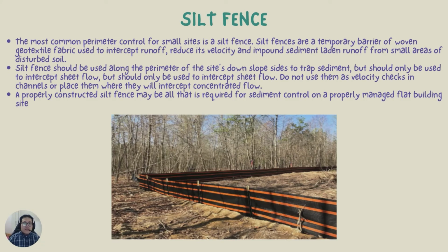So the next BMP is the silt fence. Basically, it is the most common perimeter control for small sites. Silt fences are temporary barriers of woven geotextile fabric used to intercept runoff, reduce its velocity, and impound sediment-laden runoff from small areas of disturbed soil.